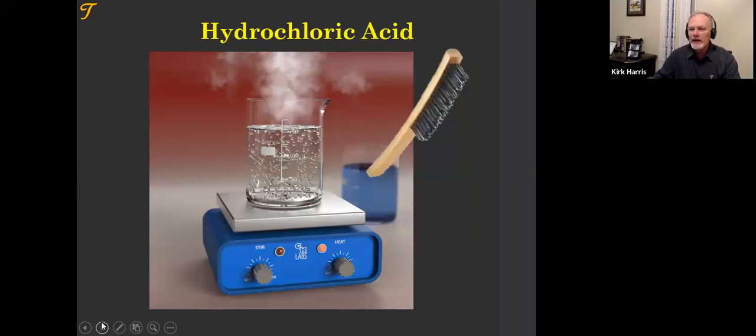In hydrochloric acid, when we put the cement in, once again, an insoluble salt surrounds that as it tries to invade the cement. So we test it in various ways. We stir it to keep transport occurring. We even take them out and scrub it with a brush to get rid of the insoluble salts and put it back in. We can get very aggressive for how we allow the acid to attack it.